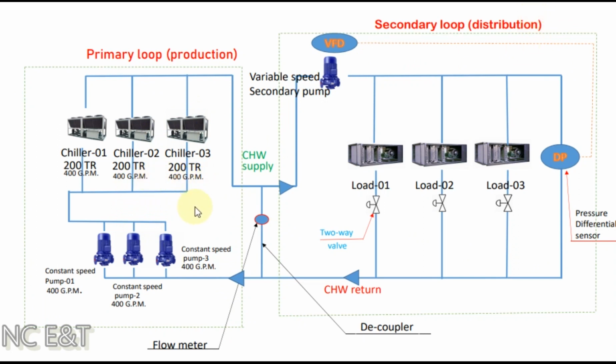As we also know, a conventional chiller is designed based on two fixed parameters. Number 1, a constant flow of chill water through it. Number 2, a fixed set point temperature at its outlet. So to provide a constant flow of chill water through it, we need to use a constant speed chill water pump having a low head only to cover the chill water flow through the chiller. This pump arrangement can be any of two types, tandem or headed, and this pump arrangement we will study in a separate video in detail.